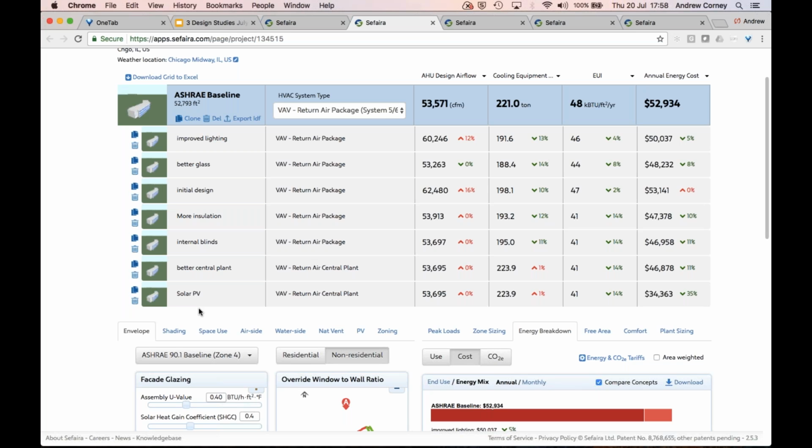So there's no constraint on that. PV data, we currently use the vanilla PV module in EnergyPlus, and you can control things like the efficiency and obviously the size and orientation of the panel, but you cannot select specific brands.